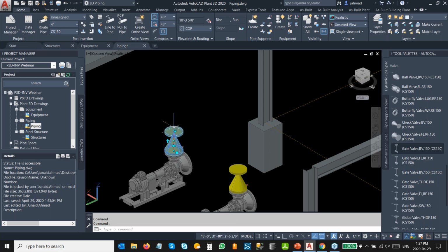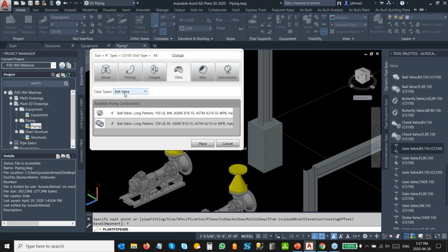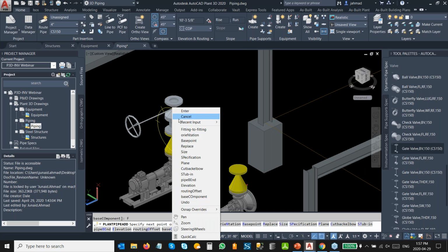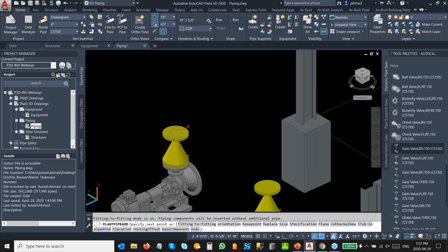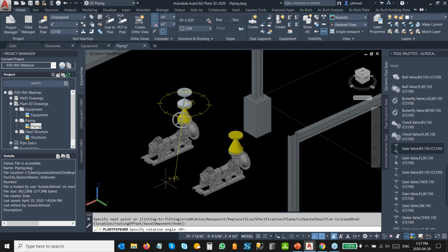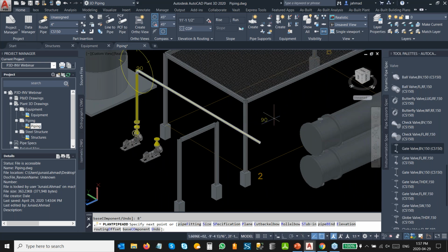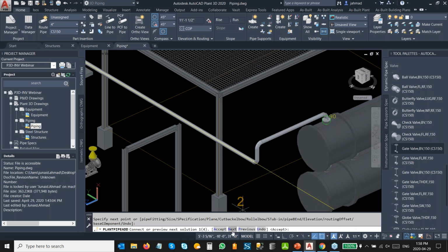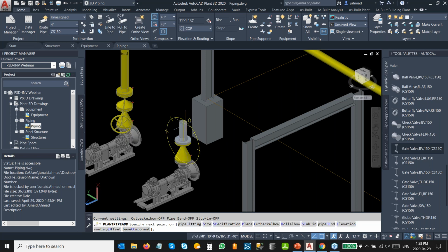Next, I can click on the check valve, use the plus sign grip to continue the pipe routing, right click, pipe fitting, and I'm thinking to select a double disc flanged gate valve, and I can do a fitting to fitting connection. Define the orientation or rotation for the hand wheel, give the pipe a value of length, and I can use the auto routing to snap to the nozzle on this exchanger, accept the placement, and I'll do similar steps quickly on the other check valve as well.